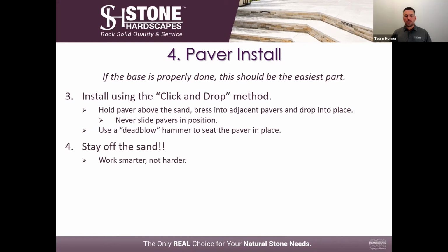Stand on the pavers. Use the pavers as a pedestal. Use the pavers as a loading point. When you finished with your bedding sand, you should not walk on that again. Lay your pavers, start using your pavers as your decking area. Work smarter, not harder.